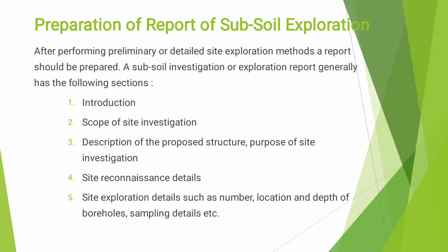After performing a preliminary or detailed site investigation, as an engineer, a report should be prepared. A subsoil investigation or exploration report generally has the following sections. First one, introduction of the project, and second, scope of site investigation. What is the main scope for conducting the site investigation for the project? Next, description of the proposed structures.